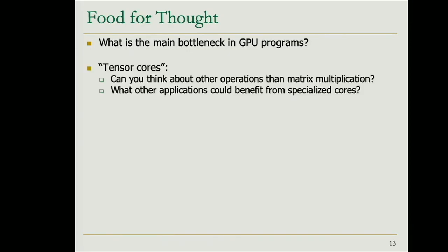About these tensor cores, we are talking about them as very useful and very efficient for training deep neural networks, essentially to perform matrix multiplications. As you may know, not only in training but also in inference, when we are running neural networks, what we do is map the convolutional layers, among other layers, as matrix multiplications, and that's why we can easily map them onto these GPU cores and achieve very, very high throughput.